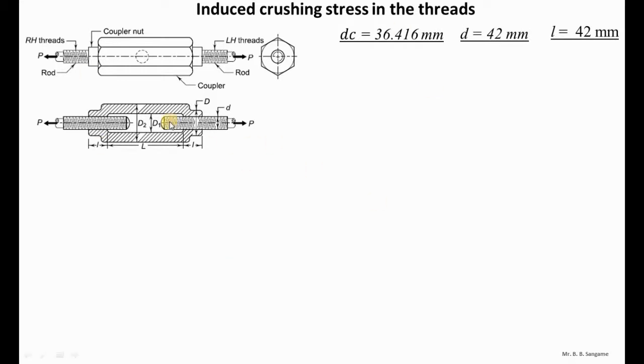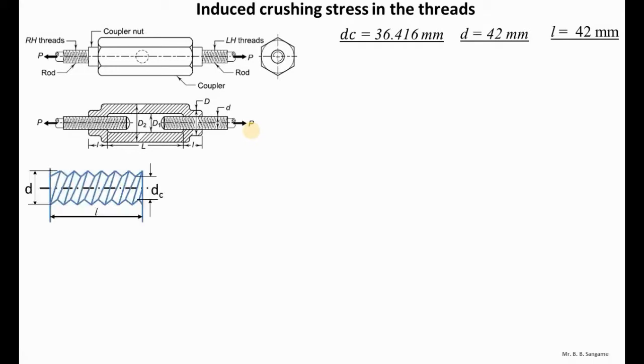For these selected values, I am going to check how much crushing stress will get induced after the application of force of 78,000 Newton. Okay, for the design load of 78,000 Newton. Here you can see the threads. This is the length of coupler nut. After the application of force of magnitude P,